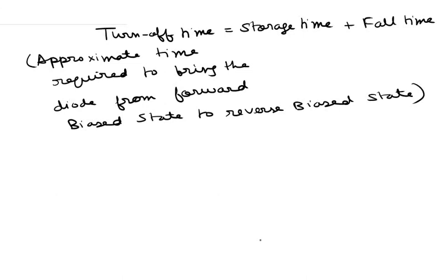Whenever the diode voltage polarity is changed suddenly, the diode does not go from the forward bias state to the steady state reverse bias state immediately, but takes some time, and this is the time frame over which the accumulation of excess minority carriers just outside the depletion region is removed to zero.